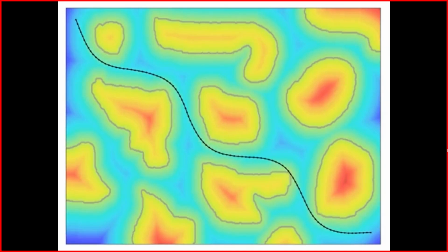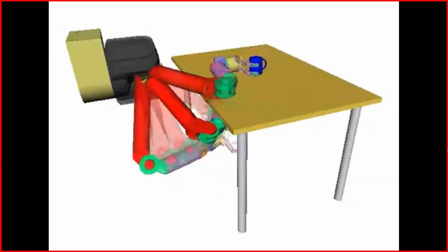And here are some examples. So what you can see here is a 2D optimization of the path with the signed distance field laid on top. And you can see here, after multiple iterations, this algorithm is actually converging to a pretty good path, which is far away from obstacles while also being smooth at the same time. So in 2D it works, in 3D it also works.